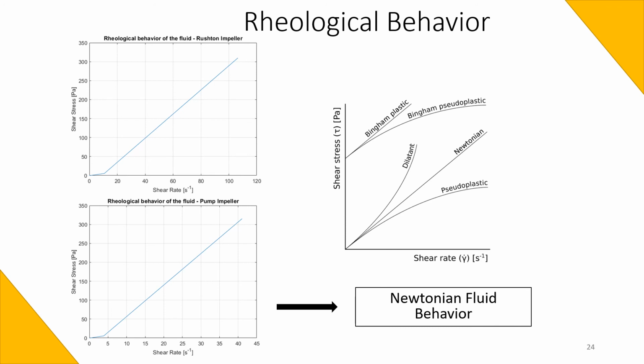If the fluid used was a high viscosity or a non-Newtonian fluid, it may cause issues. The required torque for achieving a satisfactory mixing may be very high for this type of fluids. In this order, none of the impellers used would work appropriately with this type of fluids, as they may cause a higher power consumption and an inadequate mixing in laminar flow. For this type of fluids, anchor, double helix, or screw impellers are recommended.